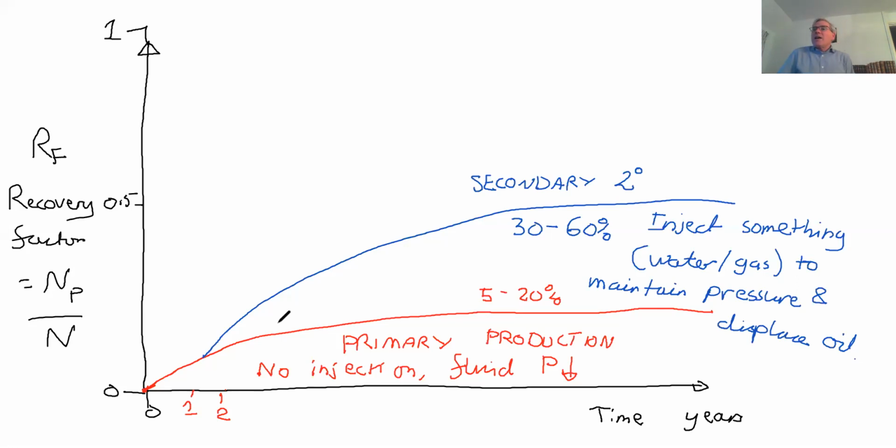So that's good. The second thing it does, and that's a distinct physical effect, is that it also displaces the oil. It pushes the oil out. Okay, it removes the oil from the pore space. So you're pushing it out. And with modern drilling, where you place your injectors in locations to contact as much oil as possible, we can get, in some reservoirs, recovery factors of 50% or even more.